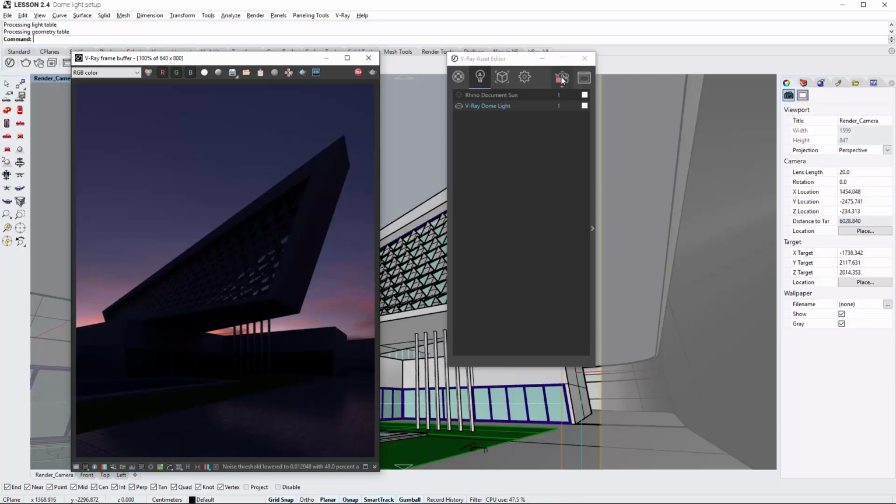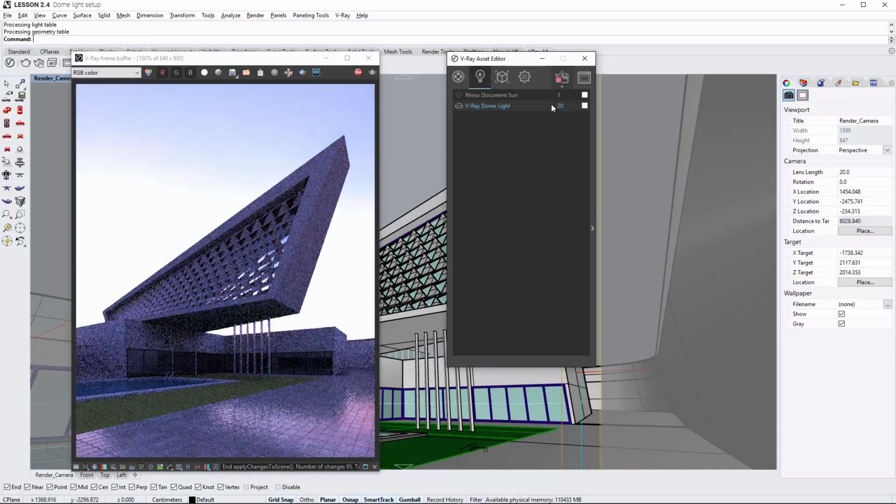This is because the intensity and brightness of HDRI images can vary significantly, so you'll need to manually adjust the light intensity accordingly. V-Ray makes this easy for you by providing a quick shortcut to the intensity parameter. For our scene, I'm going to set the intensity to 20 here. Now, open the flyout menu here to the right.